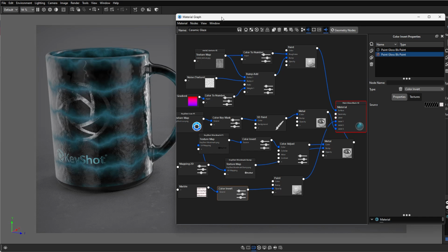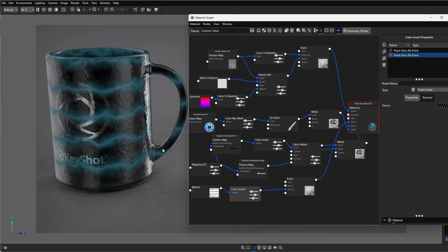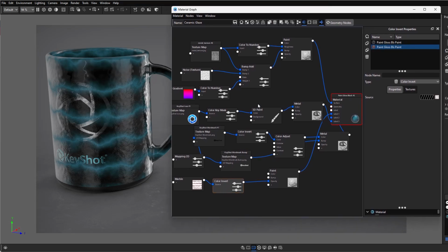Now I might want it that the handle doesn't have these veins on. Now in this model, the whole thing is one solid part, so I can't unlink materials in any case. There's also quite a nice rounded effect on it, so trying to split this surface out could prove quite laborious. So that's why in the material graph, we have the option of using the color composite.